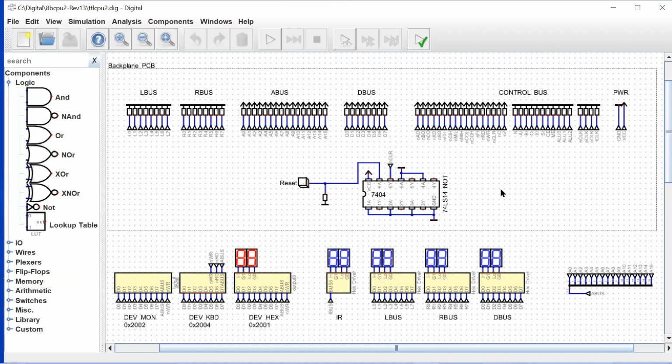So I've already started ordering components. I've found and ordered the card edge connectors that we're going to need. And I think at this point, since I've skinnied down the design here and have a direction decided on, I'm ready to go ahead and implement the first card, which is going to be the clock card. And then once that's done, I will start to work on that testing board.